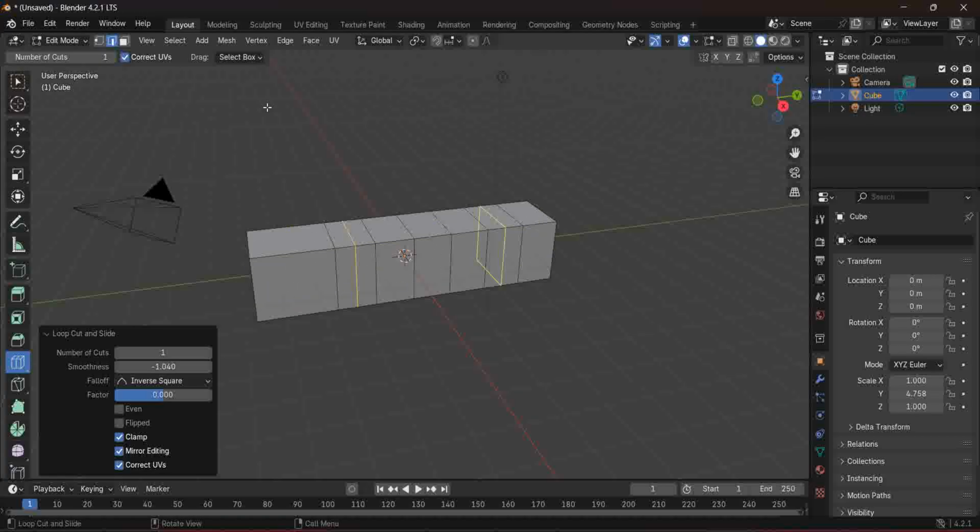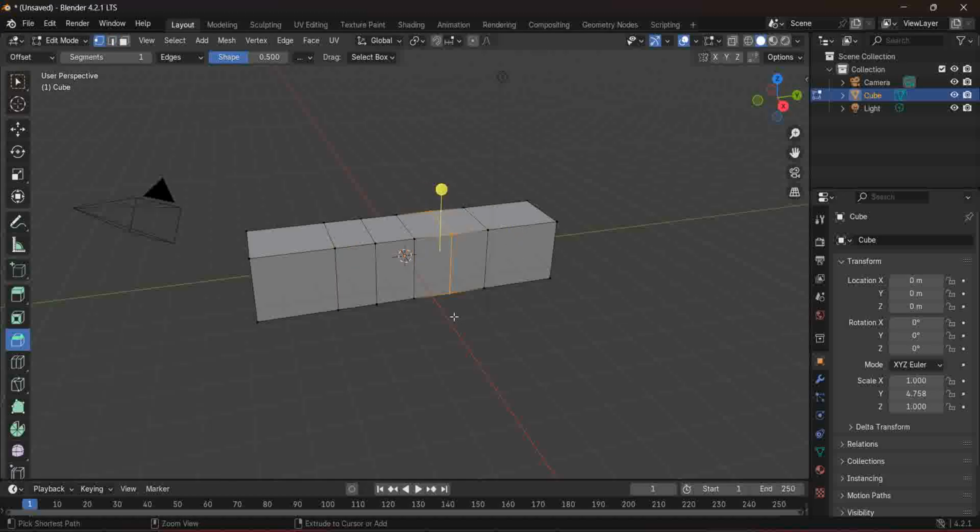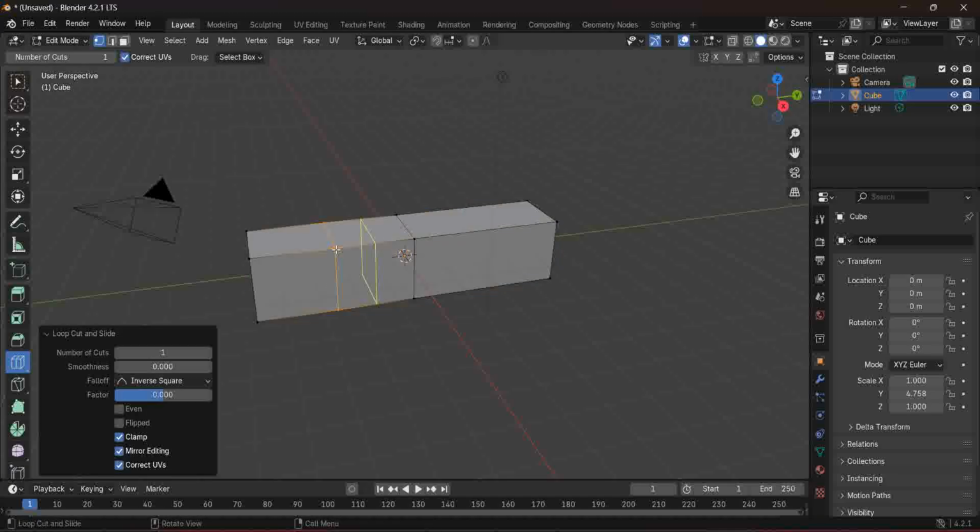So for that I'll just go to tweak first. I'll select the edge. Now my tool is set on smoothing. I'll just remove all these loop cuts. Just a second. We add a few more loop cuts here. Let's say I'm adding loop cuts here, here one and here one.